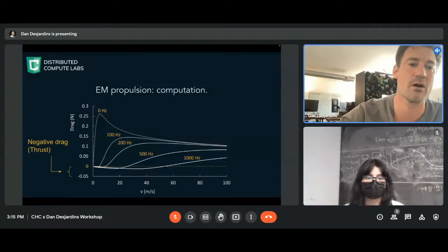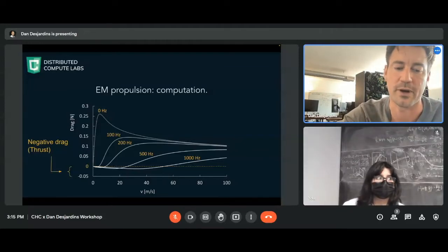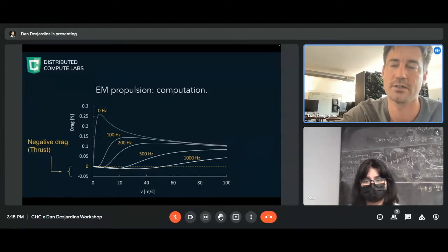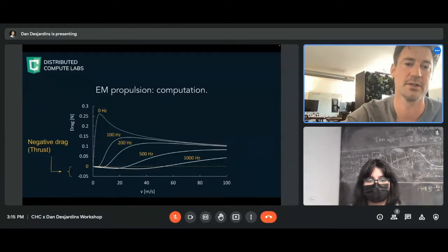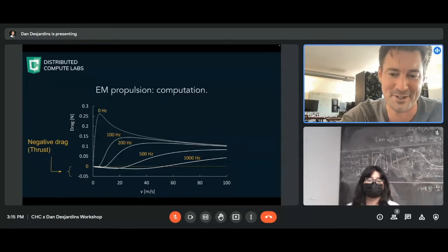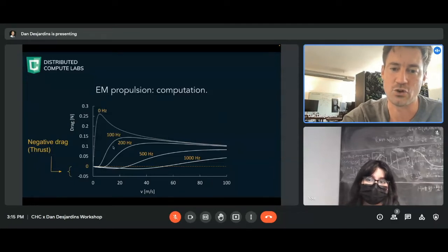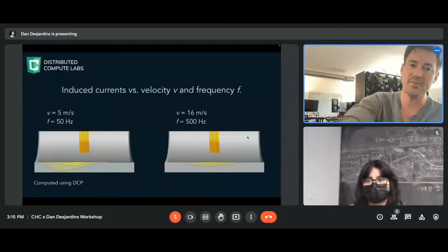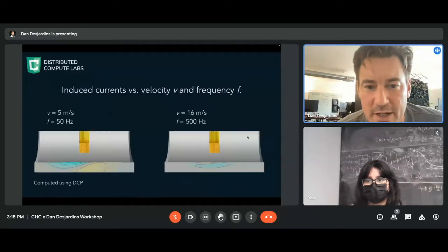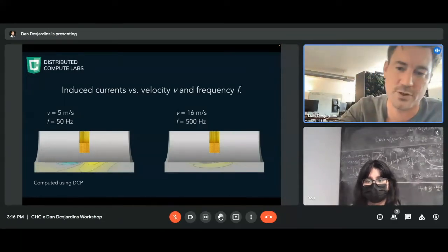Energy from the currents in the coils is definitely being induced into the pipe. So you are pumping power into this thing to make it go. So at least it's not violating thermodynamics, as it shouldn't, because otherwise we could just end this call right now and you can call me a charlatan. But let's take a look at what's happening when we're in a drag situation and when we're in a thrust situation. This is the other equation I was talking about, where we can actually calculate and show what the currents are doing inside the metal boundary itself.